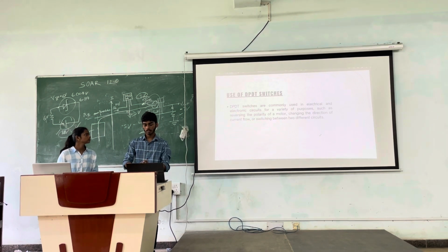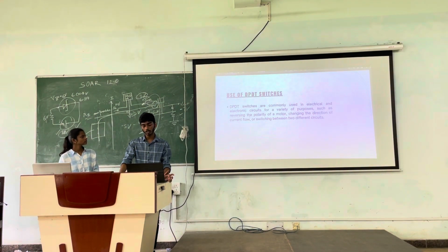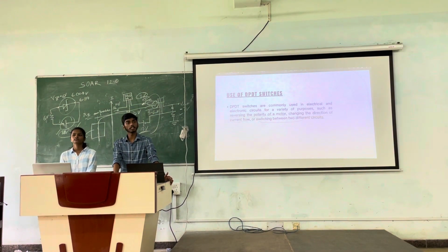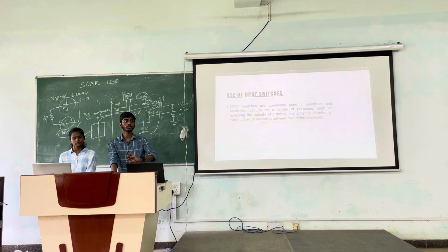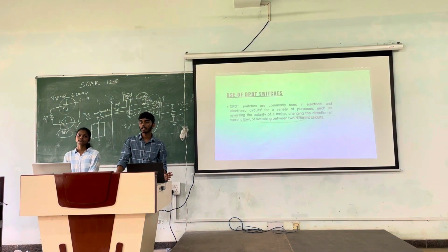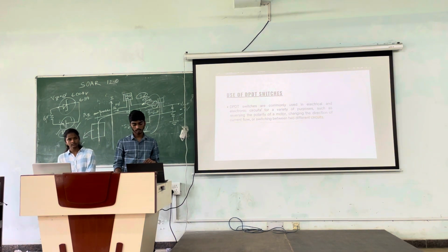Use of DPDT switches. DPDT switches are commonly used in electrical and electronic circuits for a variety of purposes, such as reversing the polarity of a motor, changing the direction of current flow, or switching between two different circuits. I want to ask you one thing. You guys know the DC motor. So how do we change the direction of rotation in a DC motor? By changing the polarity. Okay.